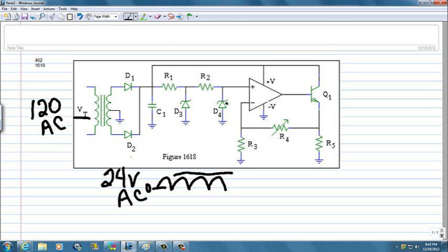The voltage of this zener diode is VA. That voltage fixes this reference voltage for the op-amp. The op-amp and transistor and feedback resistor will do what they have to do to create a voltage here the same as the voltage there.